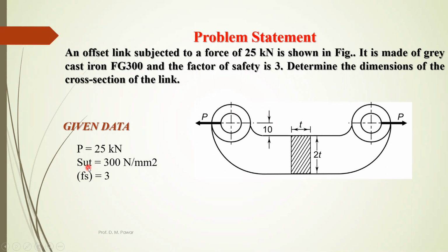SUT is nothing but ultimate tensile strength. When we design a component having ductile material, SYT is the design criteria. And if you design a brittle material, then SUT will be the design criteria. If you are designing a ductile material, then SYT, yield strength in tension, is the design criteria.